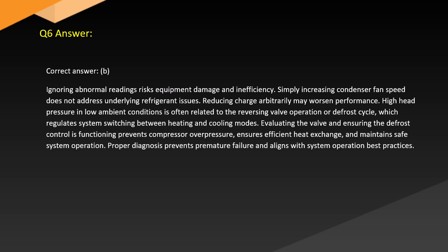Answer. Correct answer: B. Ignoring normal readings risks equipment damage and inefficiency. Simply increasing condenser fan speed does not address underlying refrigerant issues. Reducing charge arbitrarily may worsen performance. High head pressure in low ambient conditions is often related to the reversing valve operation or defrost cycle, which regulates system switching between heating and cooling modes. Evaluating the valve and ensuring the control is functioning prevents compressor overpressure, ensures efficient heat exchange, and maintains safe system operation. Proper diagnosis prevents premature failure and aligns with system operation best practices.